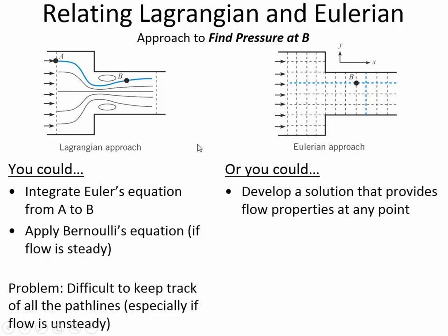And so the continuity equation is going to allow us to actually combine the two. The continuity equation will allow us to say that the fluid properties move through the boundaries, so we're going to take a control volume, like each one of these cells is a control volume, and look at the flow in and the flow out of all the properties of the fluid.